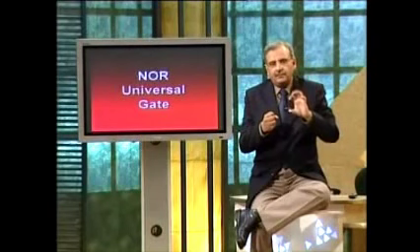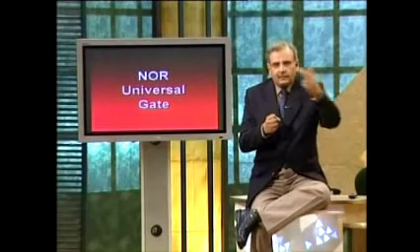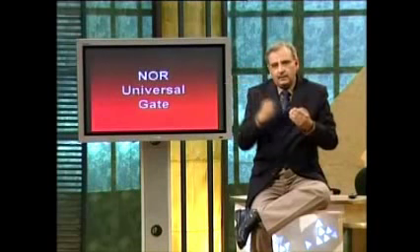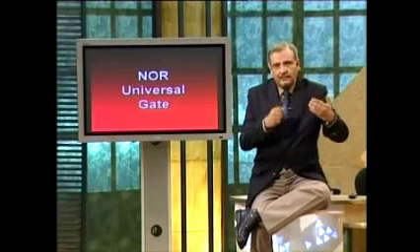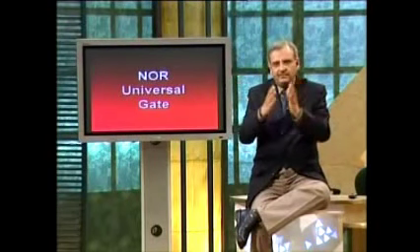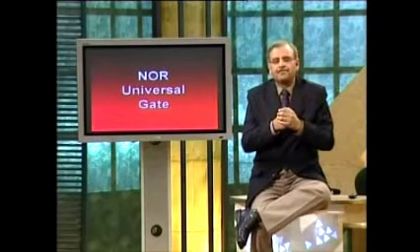If you look at the function table of a NOR gate, when all the inputs are zeros, what do you get? You get a 1. When all inputs are a 1, what do you get? The output is a 0. So basically, you have implemented an inverter.